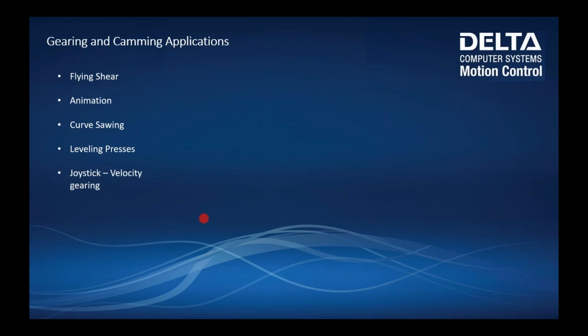Joystick, velocity gearing. This is a perfect example of where velocity gearing would be used, right? Maybe you have a joystick and you don't really want to be following this joystick one-to-one. Really what you want to be doing is gearing the velocity, right? So when the joystick goes a little bit positive, well, your velocity is slightly positive. When it goes heavily positive, maybe you have a faster velocity, and the same with on the negative side. So this is a perfect example of where velocity gearing is helpful.